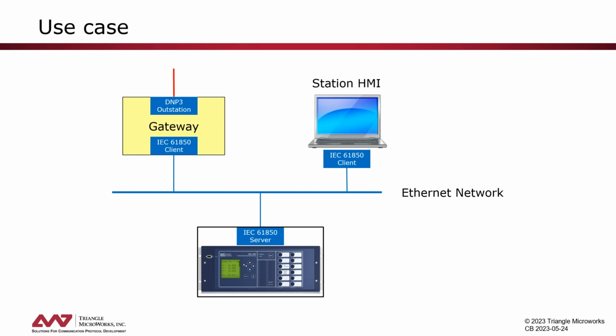mapping. So basically, the situation that we have now is we assume we have an IEC 61850 substation that we created. So the local communication is always IEC 61850. We also have a local HMI, but as the communication to our control center, we are still using DNP3. So our gateway now has to convert from IEC 61850 to DNP3.